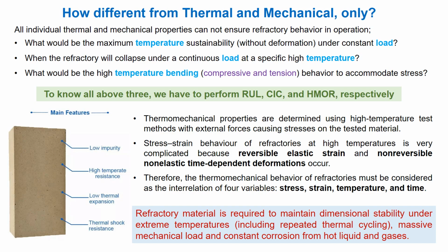Let us start by explaining the difference between individual thermal and mechanical with thermomechanical properties. All individual thermal and mechanical properties cannot confirm the high temperature refractory behavior in operation. Thus, a few common questions are obvious. What will be the maximum temperature sustainability without deformation under constant load? When will the refractory collapse under a continuous load at a predefined temperature?